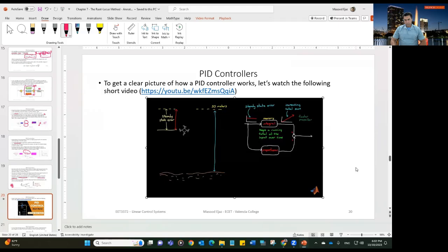These two paths, the proportional and the integral path, work with each other to drive the error down to 0. And with this controller, when the drone is hovering at the desired altitude of 50 meters, the proportional path is doing nothing since the error is 0. But the integral path has been summing and subtracting values until it came to rest at 100 RPM. Remember, this is what we said was needed for the drone to hover. And that output from our integrator will not change since the input to the integrator at this point is 0.